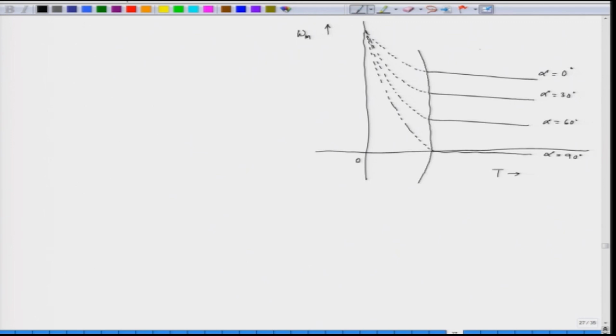So, this is the continuous current operation, and this region is the discontinuous current operation. And what about the no load speed? The no load speed for discontinuous current operation is given by V m by k phi.